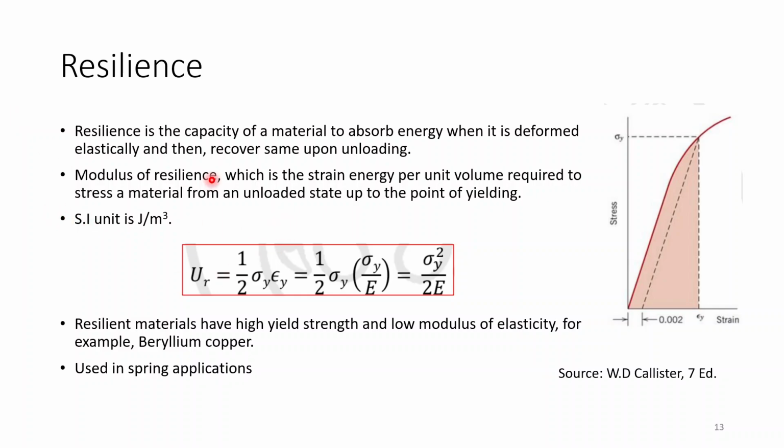So from this curve you can see, up to the yield point, you take this entire curve and you integrate it. You can either divide this curve into small rectangles and measure the entire area, or, when the data is available for various data points on the curve, you can use that method. Otherwise this can be approximated in terms of your yield stress and your yield strain.